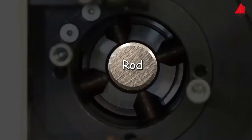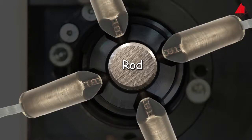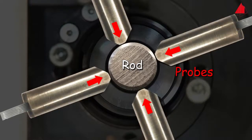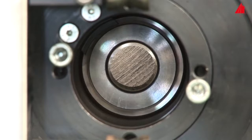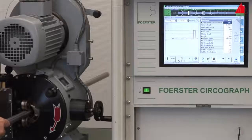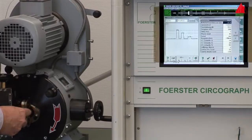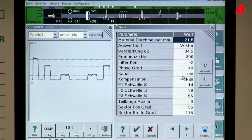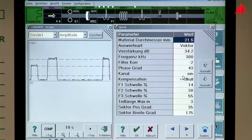Here, the rod is not only scanned by just 1 probe, but in fact by 4. And each of the probes is equipped not only with a single coil, but with several ones. The probes are positioned radially at a small distance from the rod surface. During operation, they rotate around the rod at high speed. Meanwhile, the rod moves through the machine in longitudinal direction. Here, several frequencies are used for testing. Thereby, the penetration depth of the eddy currents can be varied. This helps to determine not only the location of the defects, but also their approximate depth. And this is where eddy current testing really starts.